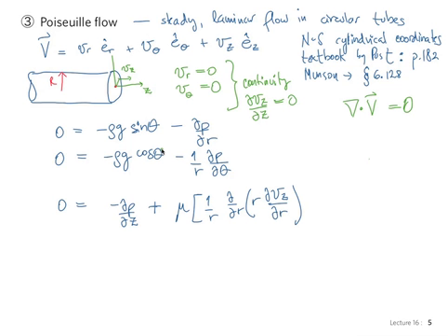Because v, the velocity, is a field. It changes value with x, y, z. It's a different value in every point in space, potentially. And this is what happens here. This is not what happens. Actually, in this case, we don't have any acceleration in this space. In this case, in addition to being steady, the particle of fluid as it moves along doesn't experience any convective acceleration. All acceleration is still here, both unsteady and convective acceleration.